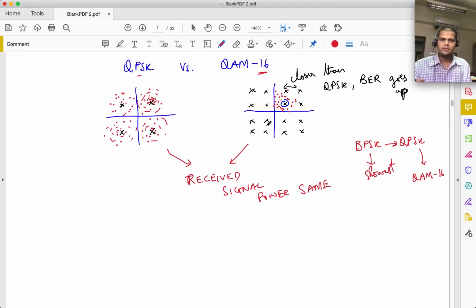So with your Wi-Fi, if you're, let's say, close to the Wi-Fi access point, you can transmit data at a higher rate. You might notice that. But if you're far away, then your transmission rate actually goes down. So what your Wi-Fi card is constantly doing is looking at these constellation points and seeing, if I transmit using QAM16, what is my bit error rate going to be?